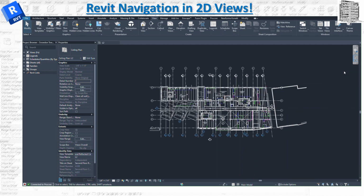Zoom to fit, so it's basically whatever you have in that space is going to put it in the window. All to fit, like everything, if you have any other drawings or anything right here in the space, basically puts everything in one window for you. And this is a great tool if sometimes you're missing some items in your whole space and you cannot find it. Do these zoom all to fit. It basically is going to give you the whole area if there is anything drawn on that space.